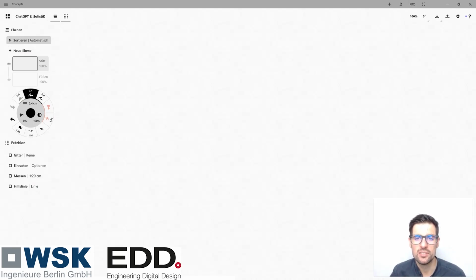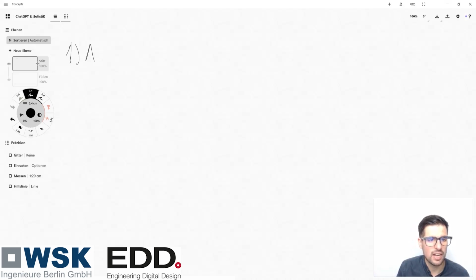Before jumping into ChatGPT, what we're going to do is to draw up a plan of the different steps we are going to follow so that it's more or less clear. And basically, as you know, Sofistik is defined into different modules, and we're going to start with the module named Aqua. And with this module, what we define is basically both the materials and the cross sections of our model. And that should be pretty straightforward.